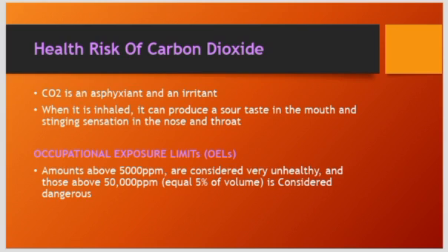When it is inhaled, it can produce a sore taste in the mouth and a stinging sensation in the nose and throat. The occupational exposure limit for carbon dioxide: amounts above 5,000 parts per million are considered very unhealthy, and those above 50,000 parts per million, which is equal to 5% by volume, are considered dangerous.